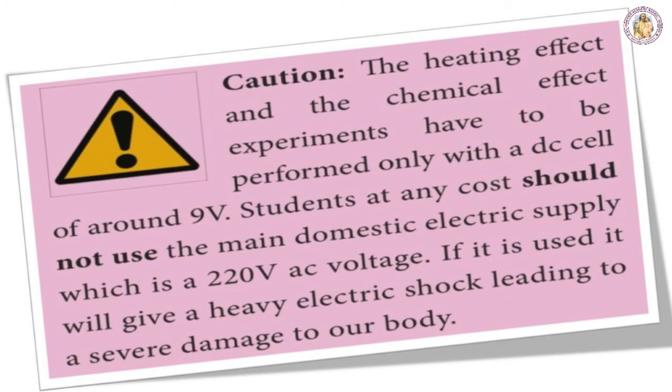Caution: the heating effect and the chemical effect experiments have to be performed only with a DC cell of around 9 volts. Students at any cost should not use the main domestic electric supply, which is 220 volt AC voltage.